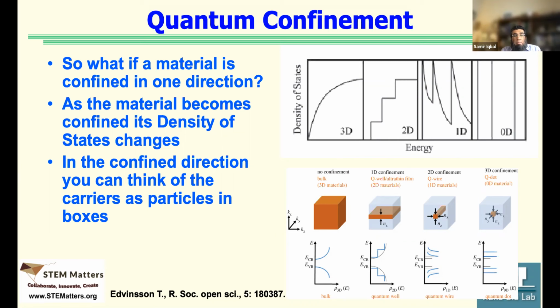But semiconductor materials cannot just start flowing. So in semiconductor materials, two conditions need to be met. There have to be free electrons that we can pump energy into and they can jump from the valence band to the conduction band. That's one condition. The second condition is there should be energy states available in the conduction band, which they can fill, and then they should be able to transport.